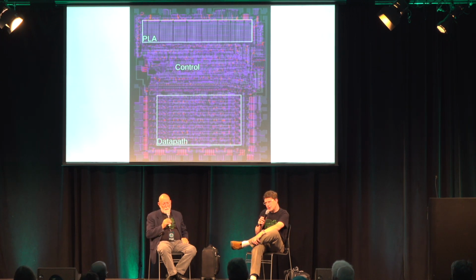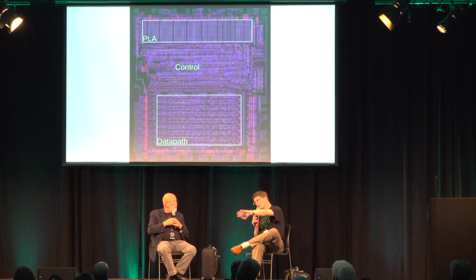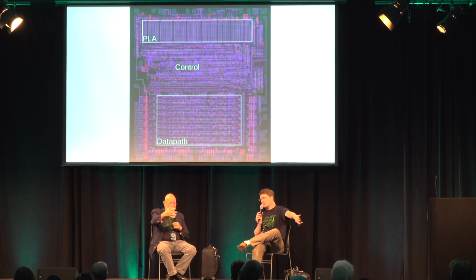Yeah, some design stuff. So we called that, the top there, we did call it a PLA, but what it is is a NAND gate. So they're in series transistors up there. I think that's correct. Well, let's see. So you've got the instruction register in the upper right-hand corner. Is that it? Right. And then what you do is you pump the 8 bits of the opcode from right to left across that, and it decodes the different instructions.